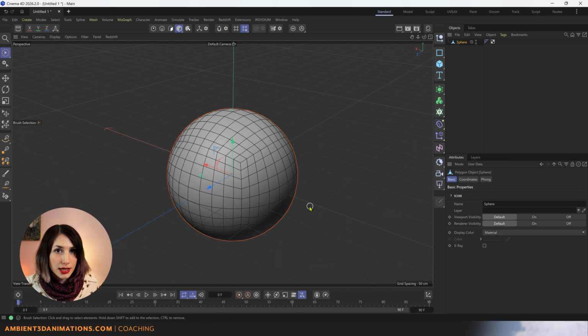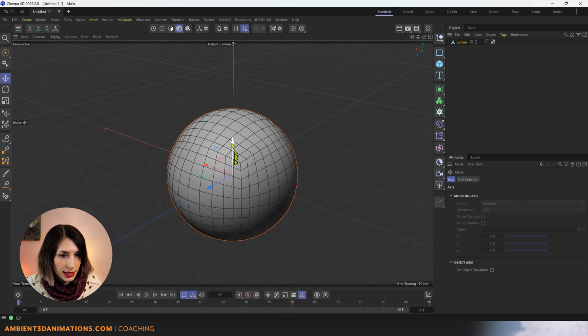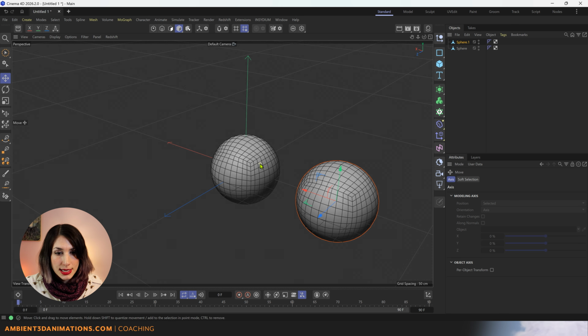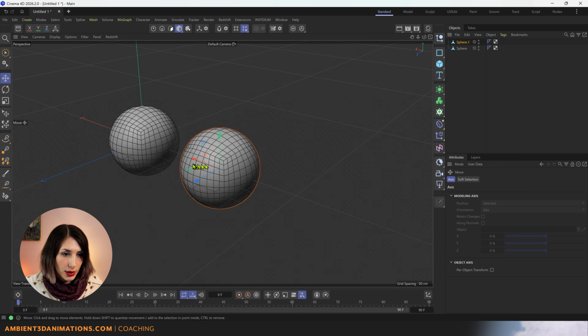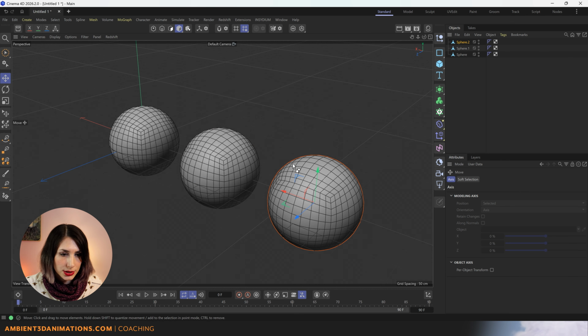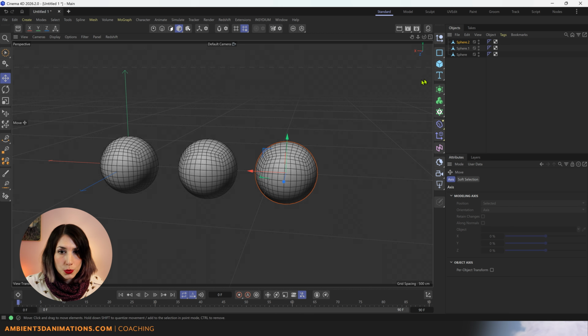Now I'd like to use this for a few examples. So let's actually duplicate this. I'm clicking on this model mode here, using the E hotkey to make sure that I have my move controls here. And now I can hold control, click on an arrow, and move this over to the right. Now we have a duplicate. I want another duplicate, so I'll do that again. Dragging my mouse, holding control over to the right. Clicking on that arrow. We have 3 of these in here.